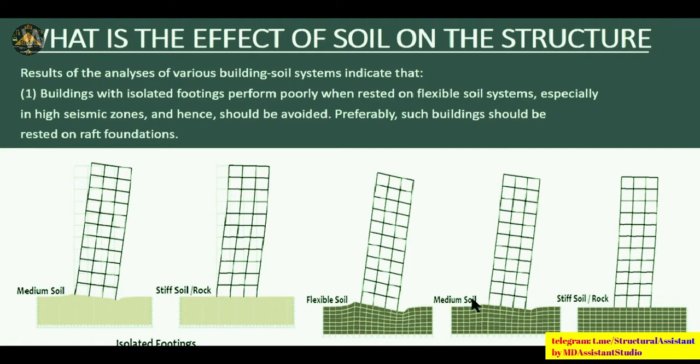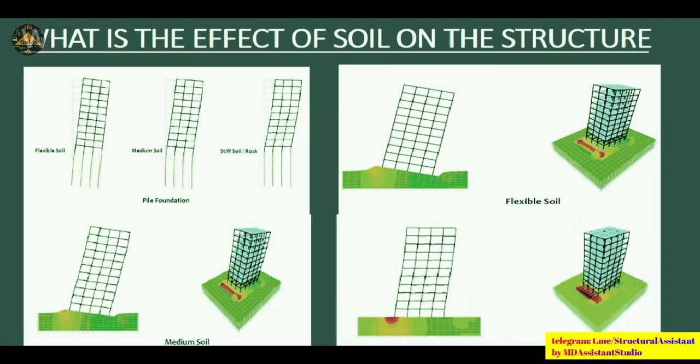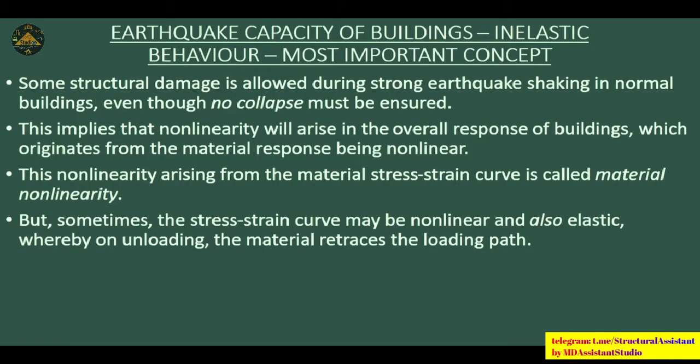And on flexible soil, medium soil and stiff soil, the behavior is different. So basically soil also has a very important effect on the structure. The stiffer the soil is, or the more the bearing capacity of the soil, the more fixity it will provide at the foundation level. Basically there is also a very important concept that we should understand, the material non-linearity.